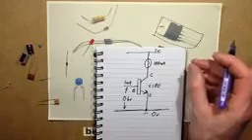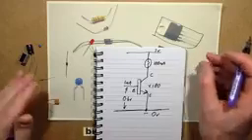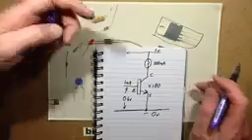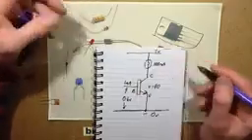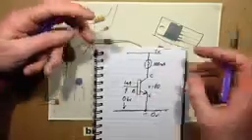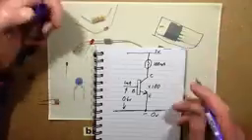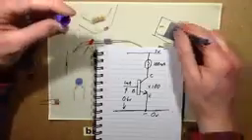You can use it to switch quite a modest current without having to worry even about applying a heatsink to it. Traditional transistors would have a slight voltage drop across them, and that would result in heat dissipating. So MOSFETs are much better for that.